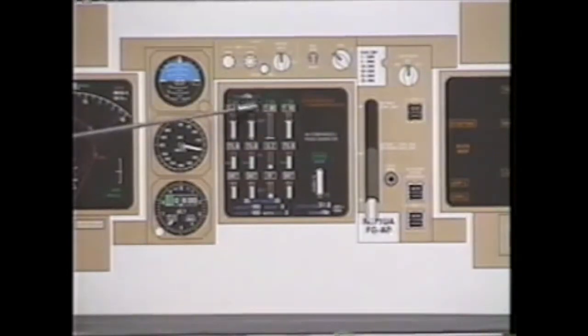Thrust mode enunciation, in this particular case, go around or GA is enunciated with the limiting EPR of 1.50. Various thrust modes we can encounter here are TO for max EPR, D-TO for reduced EPR, climb, climb 1, climb 2, continuous, cruise, go around. All of those are different thrust modes with the appropriate limit EPR displayed in green.